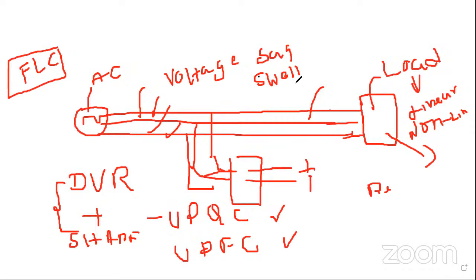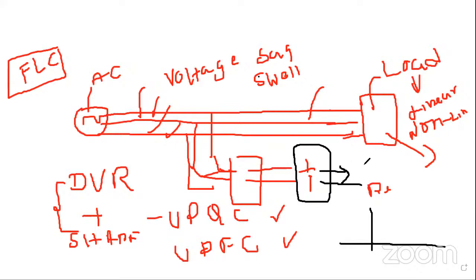Across this one, we will keep a DC link capacitor. While you are keeping the DC link capacitor, you need to initialize the capacitor voltage around 600 or 800. You can keep the DC link capacitor voltage in between. If you are initializing up to 600 or 680 or 700, the DC link capacitor needs to start from 0, then it will reach some peak value.